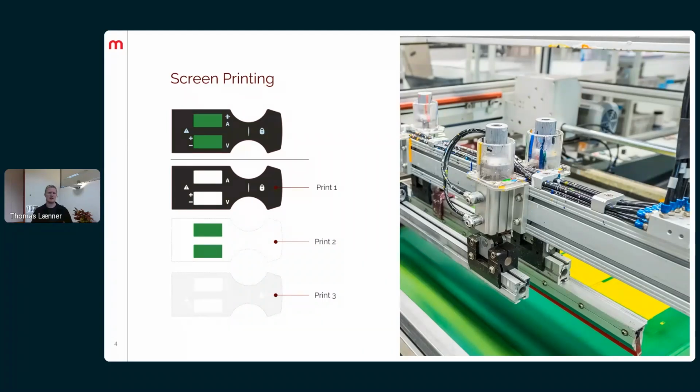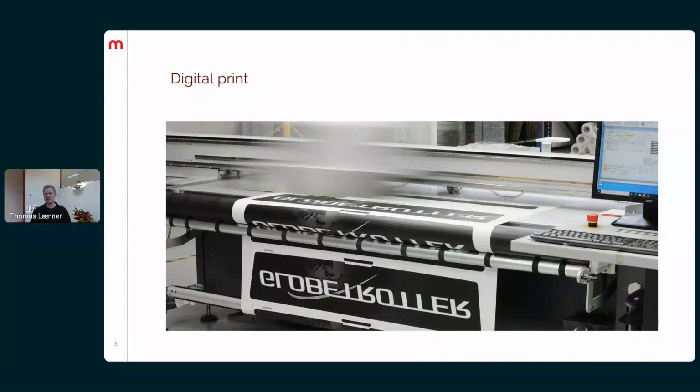Screen printing also has a bit of limitation when it comes to artwork. For complex graphics like multicolor gradients, detailed shadows and highlights, and even photorealistic artwork with many colors, screen printing becomes more difficult, and it's more relevant to look at, for example, digital printing. Digital printing doesn't require a screen for each color, it does it all in more or less one shot, meaning that the number of colors doesn't really matter. Therefore, most detailed artwork is made with digital printing today.